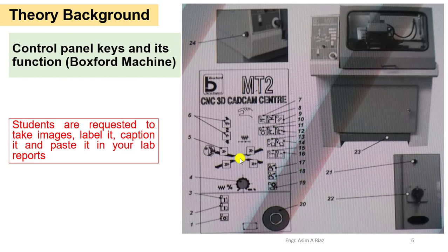These buttons, labeled 5, are used to move the turret or the work holding assembly in the lathe mode. So when you press the middle button with the axis button, the feed motion control will increase and it will start jogging. So these are the jog axis control keys.